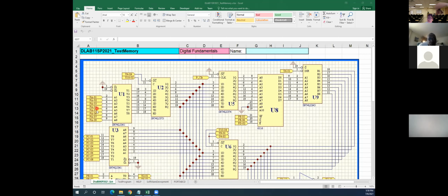Okay, so the data goes into port A. From port A it goes to U1, no problem. But you have to get the latch U2. So the data from the input here goes inside U2, not out yet, until you need your pin 1 to be 0. That's what we're talking about, enable U2. So when they're going up here, you can go back to read to verify.